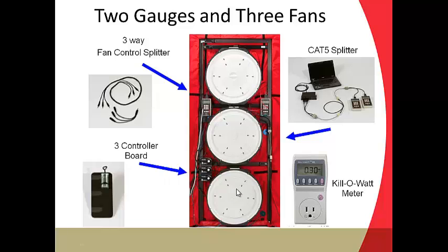And then we'll crank up the first fan and see if the voltage changes on the second one, and if it changes by more than a couple of volts, a few volts, then we know. If it goes down by more than a few volts, we'll know they're on the same circuit. We'll have to run a cord to a different one, and then we test the third one that same way against the first and second.